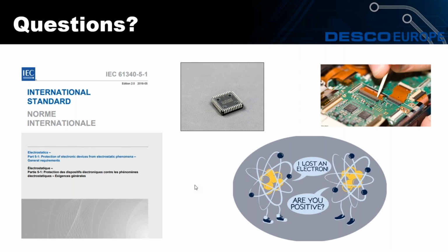And that's one of the areas where we would be very happy to come and visit and carry out an ESD assessment, where we can place a sensor inside your SMT line at various points to determine if there are ESD events, and to determine if and where an ionizer should be placed within the line.